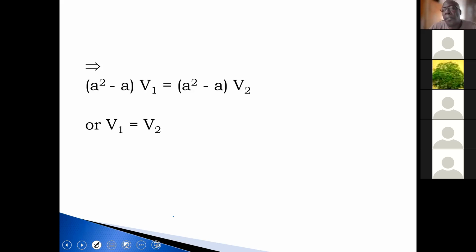All right. So for the phase to earth, we looked at just the currents in doing our analysis. For the phase to earth, or phase to ground, we looked at the voltages. And I suppose by now you get used to my network talk. We just go and amp it up a bit. So for phase to phase, we're going to use both currents and voltages. So I've used the voltage relationships to show that V1 is equal to V2.